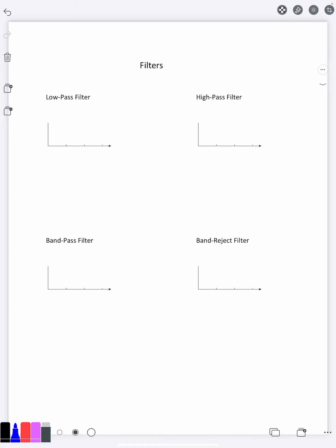For example, the human ear can only hear sounds up to about 20 kilohertz, and so any sounds higher than that, basically we cannot hear. One thing they do is filter out those higher frequencies in phone calls, and you won't even notice it because you couldn't hear the extra sounds there. And by filtering those out, they're able to have less information to send, which allows it to transmit your sound over through the cell phone to another person's cell phone much easier and with less problems.